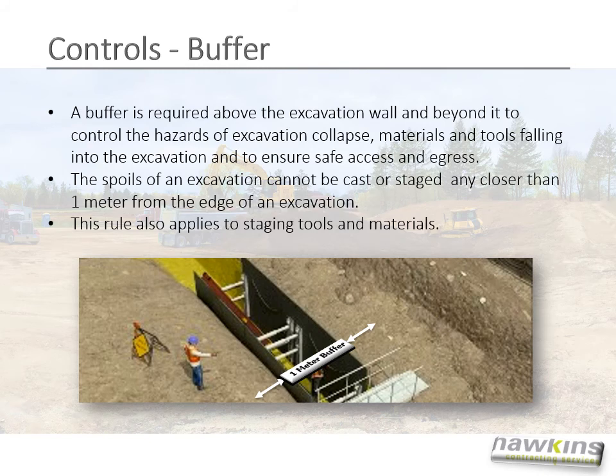A buffer is required above the excavation wall and beyond it to control the hazards of excavation collapse, materials and tools falling into the excavation, and to ensure safe access and egress. The spoils of an excavation cannot be cast or staged any closer than 1 meter from the edge of an excavation. This rule also applies to staging tools and materials.